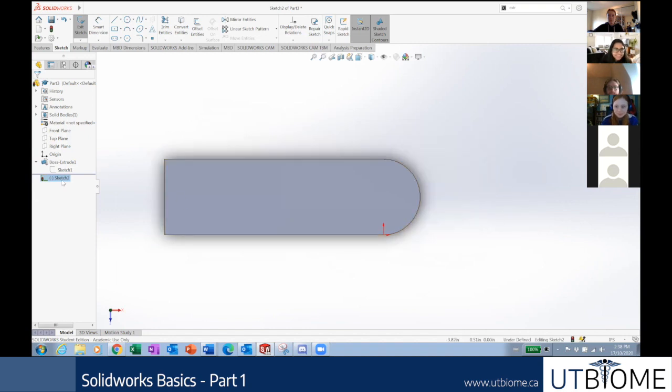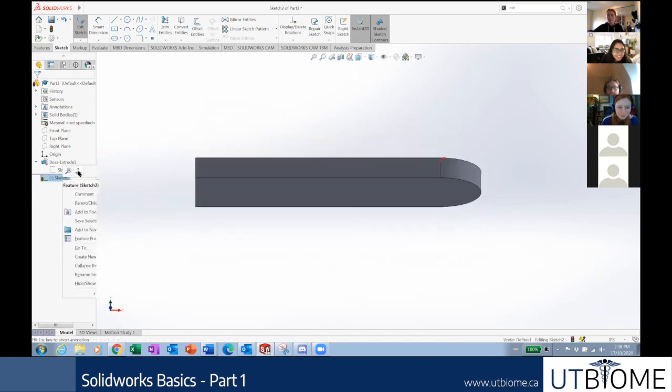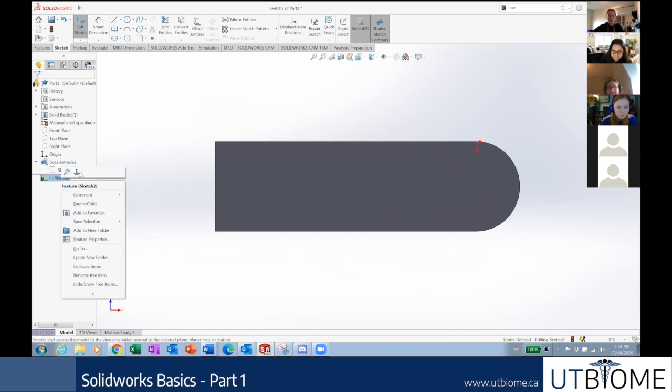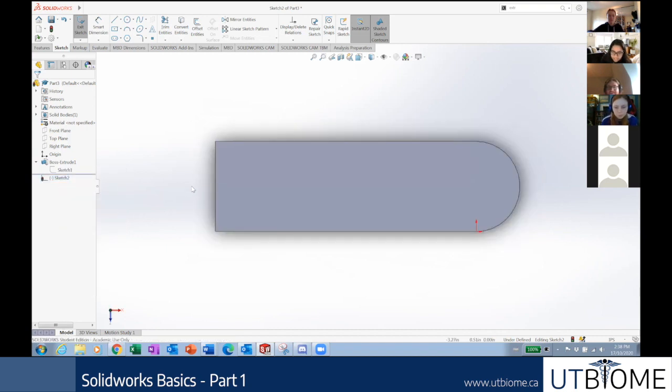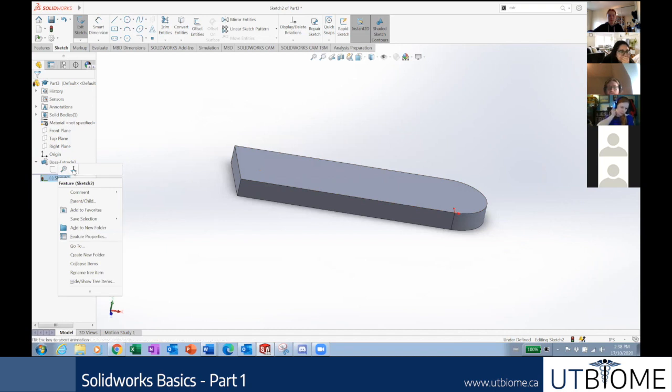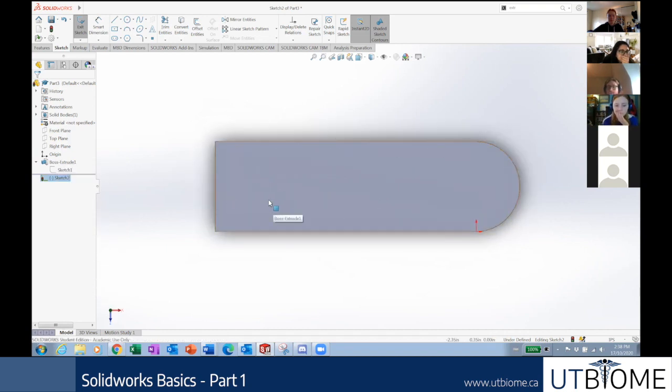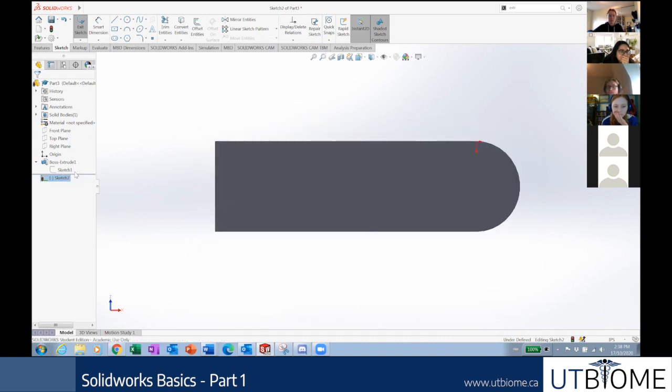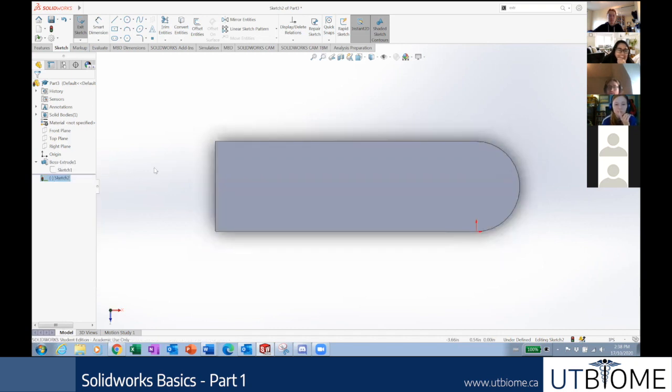Okay. You don't have to worry about this now, but I'm giving it to you in case you face this problem in the future. I go normal to, but for some reason you want the opposite side of what we're looking at. If you click normal to again, it'll flip the model around and you'll look at the complete opposite side. Sometimes that'll be useful. I can't tell you when, because I don't know. I just know I've done it before and that's why I know I can do it now. So I'm just throwing that out there, in case you have to do the flipsy, that's how you do it.